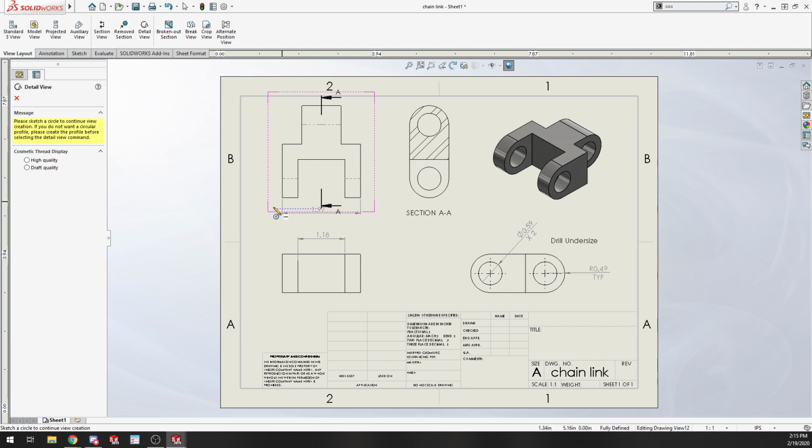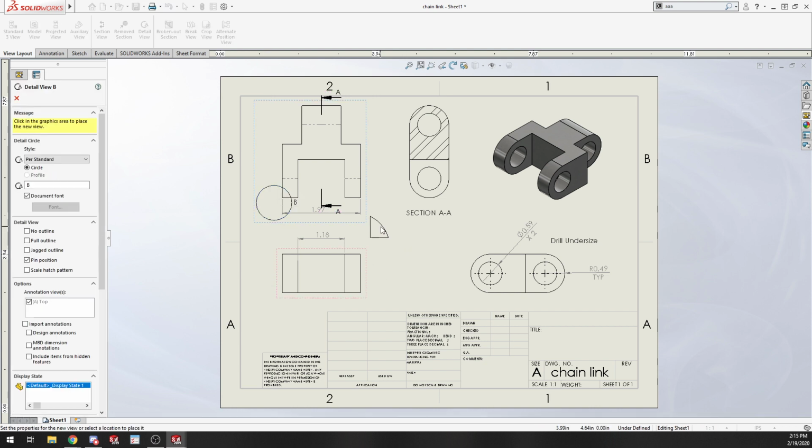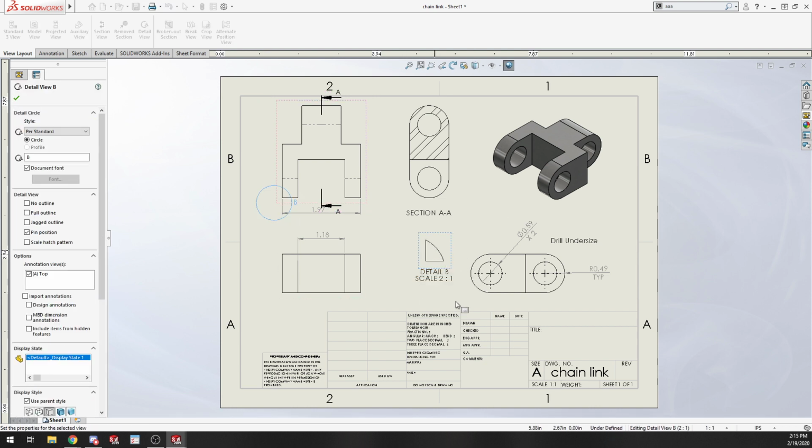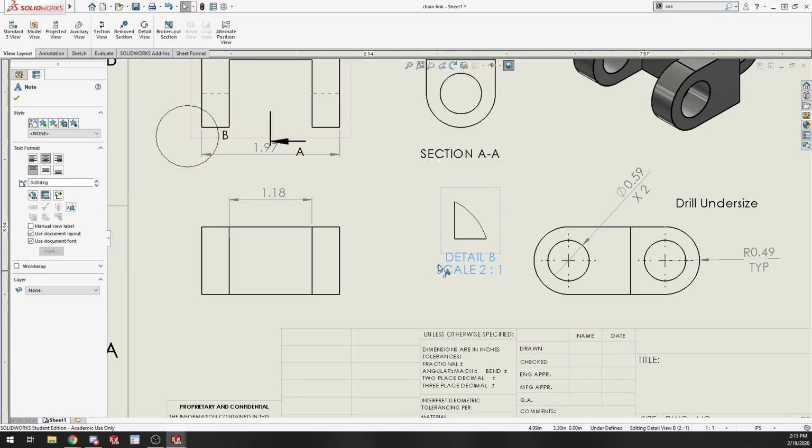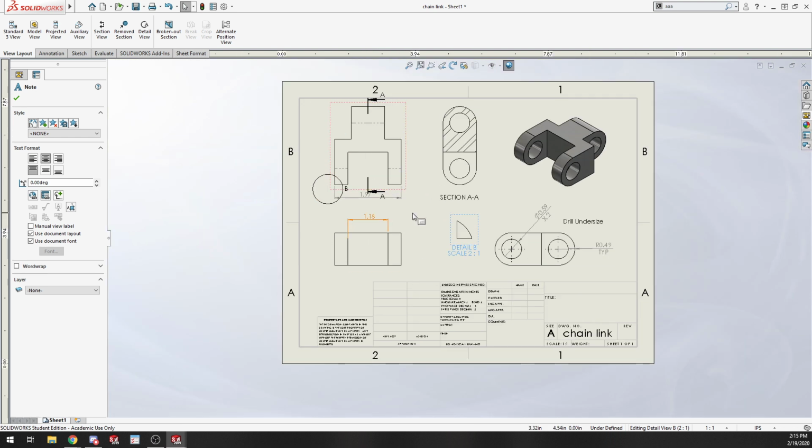So if I wanted to really hone in on this bit there, drop it right there. Detail B, it's just showing me that corner super close up. It's at a 2:1 scale. If that corner had some super nice detail or a specific radius, or a pattern on that radius, like on the edge of a cabinet or some trim molding, you might do a detail view of that just so you can see exactly what it looks like on that corner. Scaled back, everything might blend together.